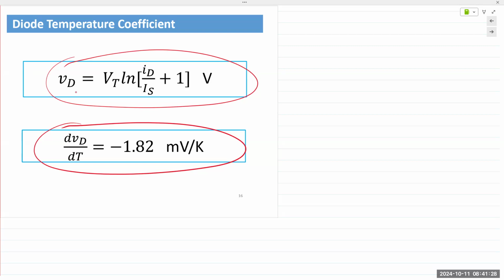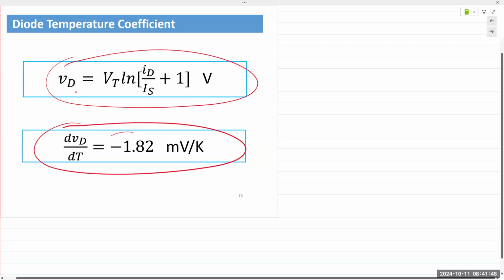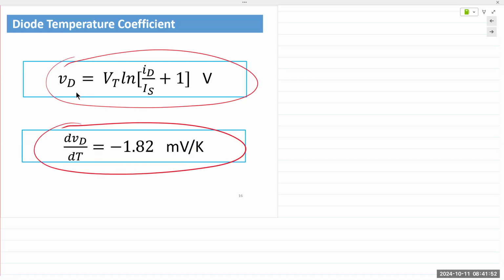And so in the book, there is a very neat example of a real life application. You take diodes and you can build a circuit around it where you can translate the change in temperature and you can create a thermometer. So most digital thermometers actually use diodes. And again, the reason is because this change right here is very linear and very constant.